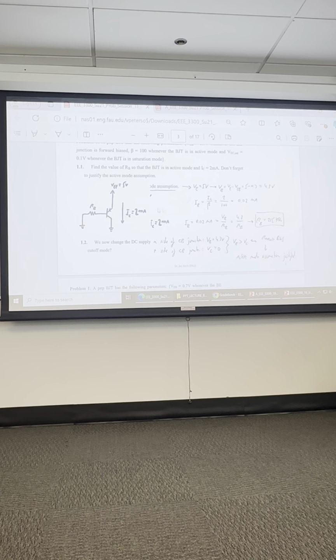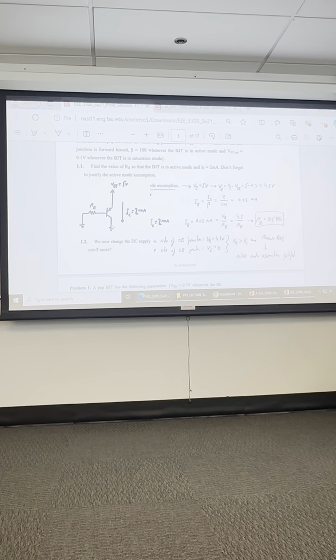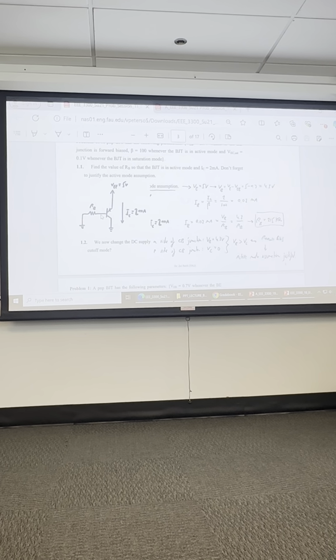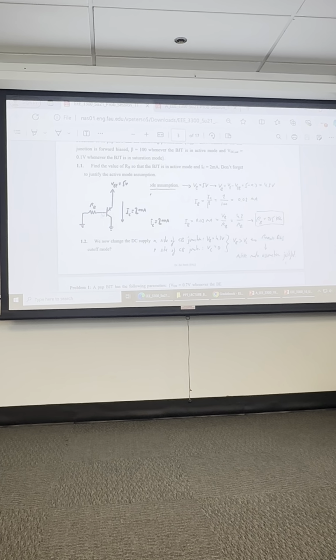And then we have a negative, now the collector. The collector is zero. Now the base is minus 5.7, so we come across another contradiction in the active mode. That means the collector voltage is greater than the base voltage on the PNP. So we have to put together what it all results in. It's no longer in active mode, and it's most likely not in saturation.